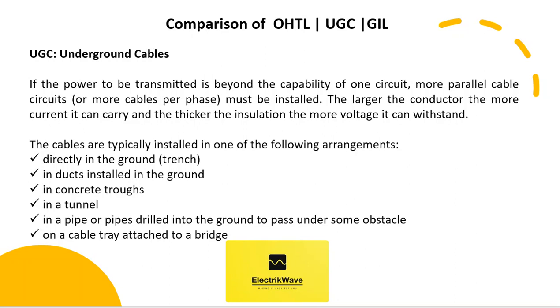The larger the conductor, the more current it can carry, and the thicker the insulation, the more voltage it can withstand. The cables are typically installed in one of the following arrangements: directly in the ground, in a trench; in ducts installed in the ground; in concrete troughs; in a tunnel; in a pipe or pipes drilled into the ground, to pass under some obstacle; on a cable tray attached to a bridge.